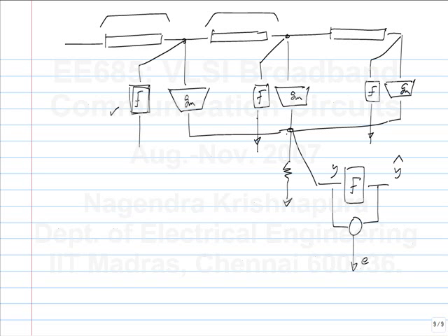In practice, you also start loading the transmission line with flip-flops and so on. That becomes very complicated, and if you do a lot of that, the equalizer may not work. So getting a high-speed continuous time equalizer working with LMS adaptation, without doing some other fiddling with it, is a difficult thing. And so far, I have not seen an implementation at high speeds of 5 or 10 gigabits per second.